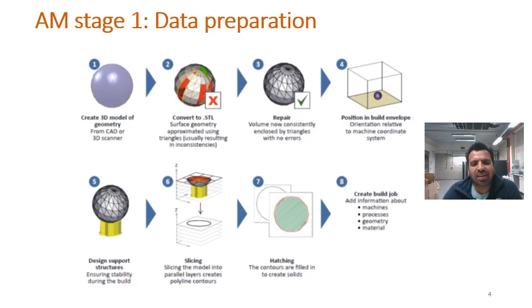The part can have some overhang structures, and you need the support structures. However, these support structures shall be designed carefully, because it will require a lot of manual work to remove them from the part, and it can also sometimes damage the part a bit.